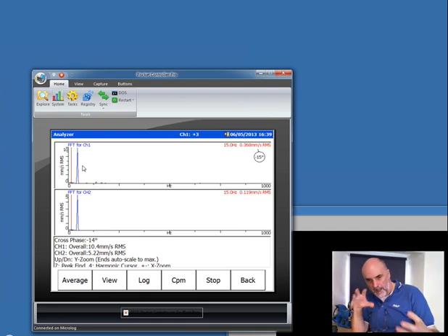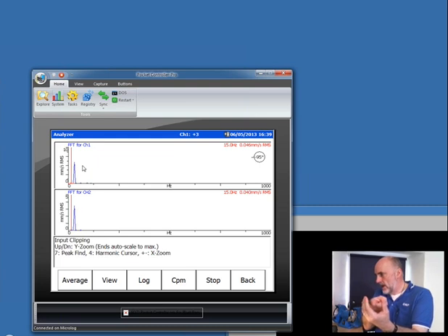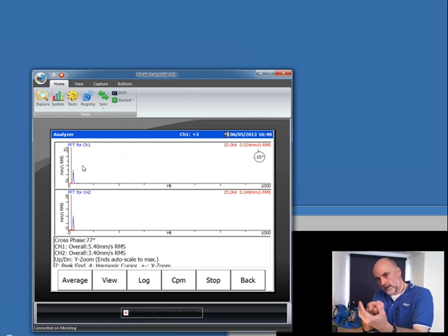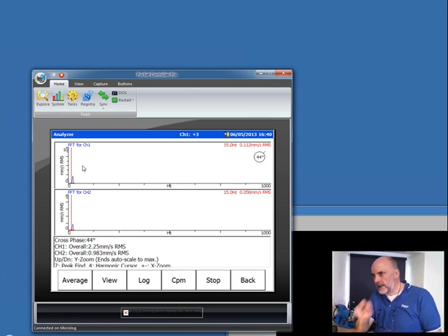Very frequent on electric motors that are getting tired, where the lacquer holding the windings is not holding the windings correctly, or if you've got wooden wedges holding the windings. If that hand is the slot where the winding sits and that finger is the winding, what you want is the lacquer to hold the windings stationary. But with age, the winding starts to move, and for one cycle of supply, you'll find it moves over to one side, comes back, moves over to the other side and comes back. So for one cycle of supply, you'll get 2 movements, slap, slap, slap, slap. And that's why you get a high 2 times in the vibration spectrum. And you can prove it's electrical by doing the switch-off test.